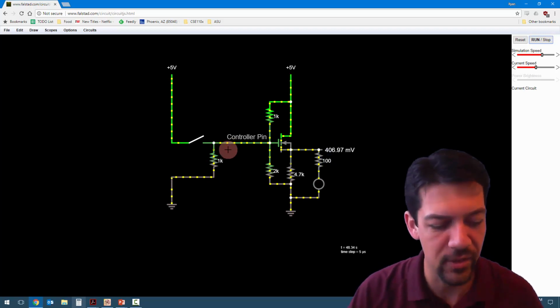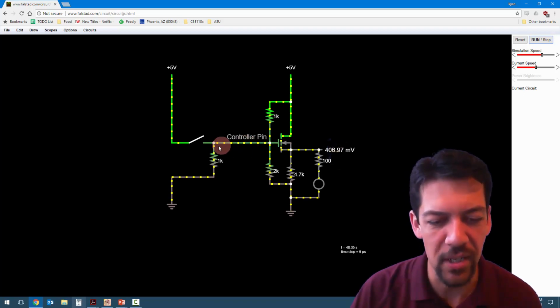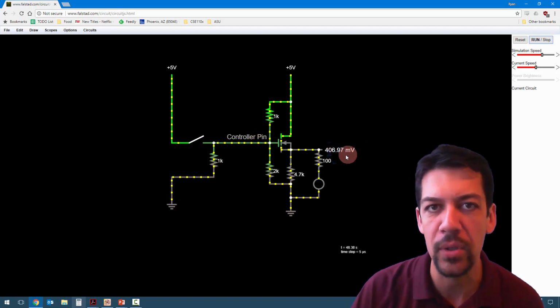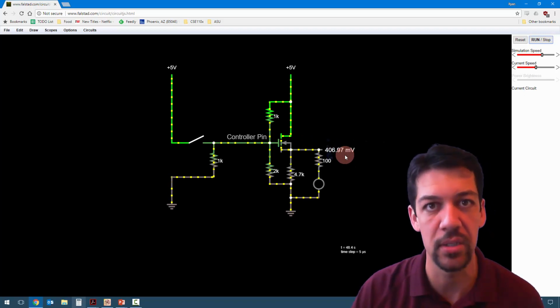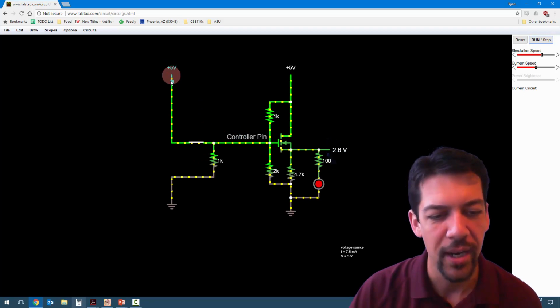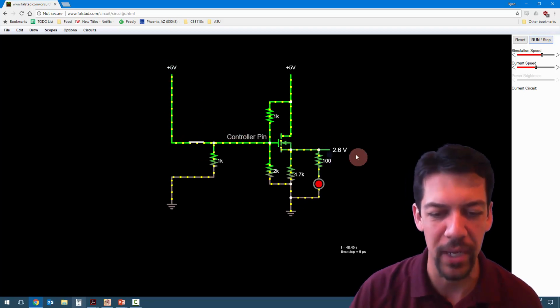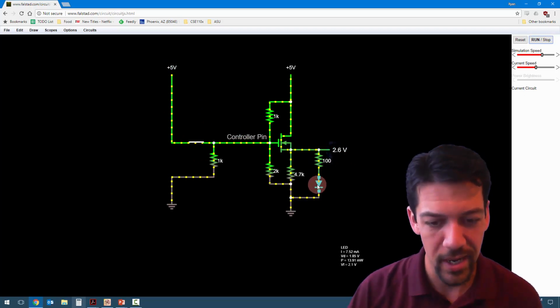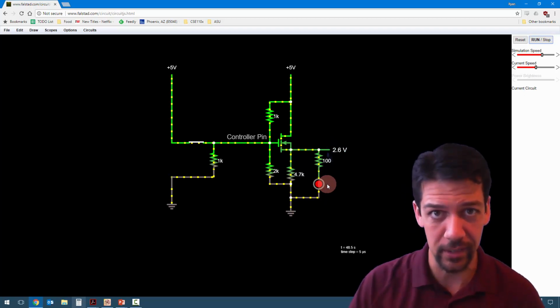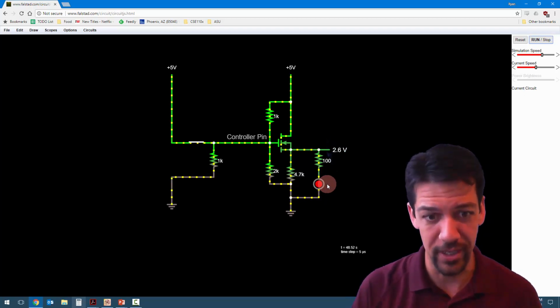So now when the switch is open, I'm still pulling it to ground, right? So I get a very low voltage on the pin that detects a strong 0. That's very clearly a 0. And then when I close the switch, I get 5 volts on the pin, a very strong 1, and my LED turns on. I'm detecting very clearly a 1 on this digital input, right?